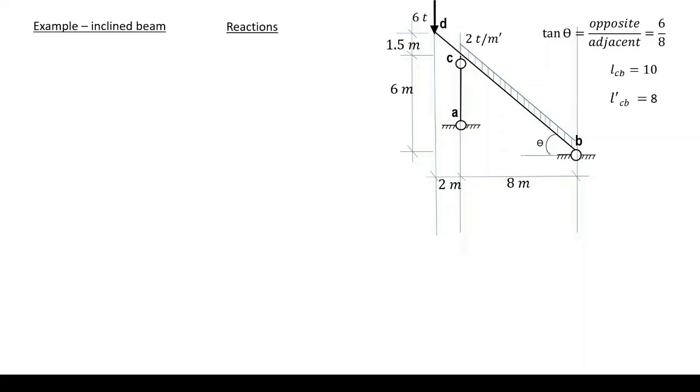To compute our reactions, we determine them. We have one reaction in the direction of CA, as CA is a link member. We have two reactions at B because it is a hinge, YB and XB. Note that the length of AC doesn't really matter in our problem.